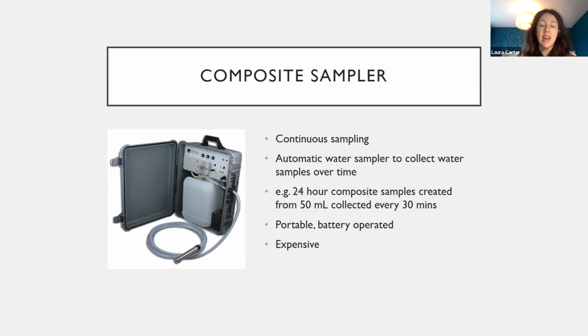However, the downsides are these are relatively expensive, and I've seen a lot of studies place them in wastewater treatment plants, for example. But if you were to leave these out in the field, in a river, then I wouldn't guarantee that it would be there by the time you get back. So potentially some downsides here. And again, if you were going to use it for quantitation, then you need to do some in-field, in situ measurements to get the data and combine this with information like flow so that you can determine concentrations over time.